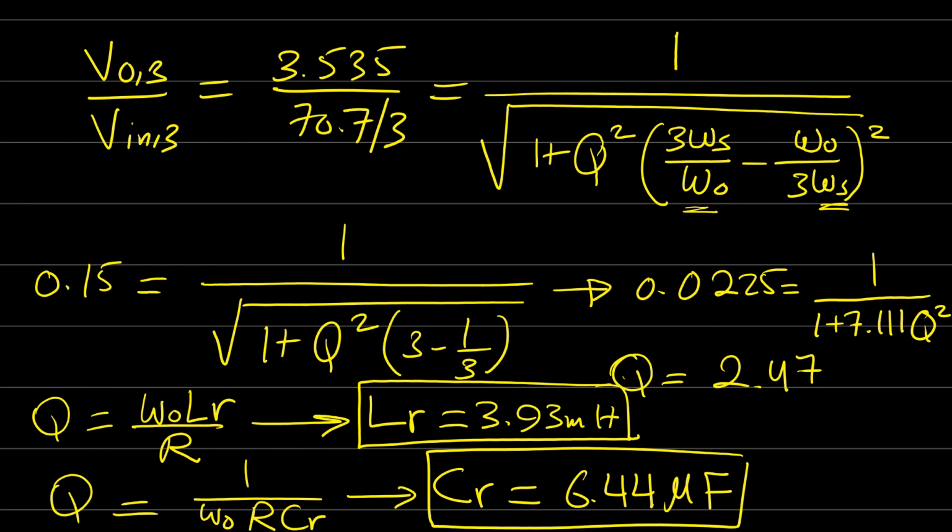If we design this inverter with these values for the capacitor and the inductor, and a 1 kilohertz switching frequency, definitely this will give a resonant converter. The current and the voltage will be in phase. By this we obtained the values of the capacitor and inductor. We designed the inverter. The second part of the question says find the value of the voltage across the capacitor.